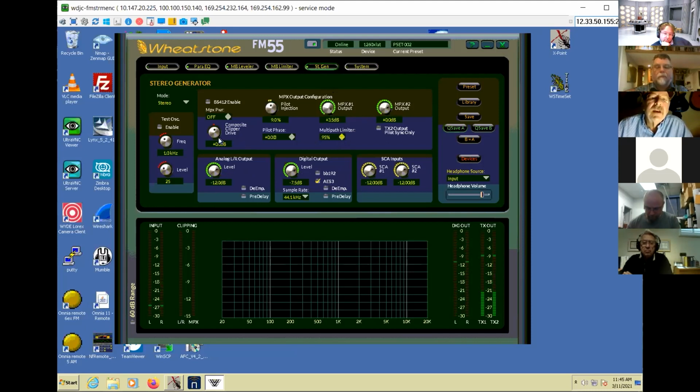Here is something that the newer models will do that you're going to love if you have an FM: multipath limiting. You know, the old saw says that stereo is worse on multipath, which it is. This multipath limiter is a smart control circuit that actually blends the high frequencies together in certain situations.